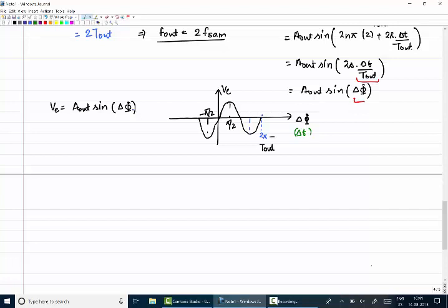For a phase error detector when my output frequency is 2 times the sampling frequency, the phase error output is like this. But if my output frequency becomes 4 times the sampling frequency, in that case this will be my phase error detector output, right? With respect to delta t, don't look at delta phi. Agree?